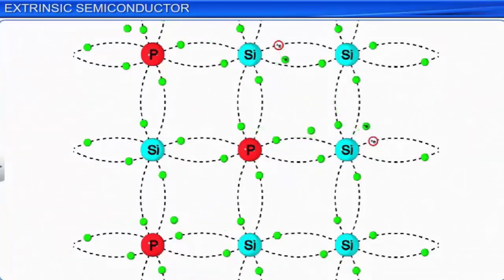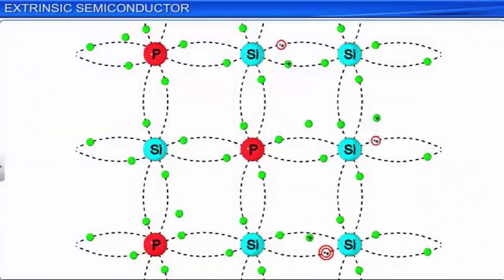Hence, in a semiconductor doped with pentavalent dopants, the total number of conduction electrons, Ne, is due to the free electrons contributed by the donor atoms, which are pentavalent dopants, and those generated intrinsically. But the total number of holes, Nh, is only due to the holes from the intrinsic source. Due to the increase in the number of free electrons, the rate of recombination of holes increases. This gives rise to a reduction in the number of holes effectively as compared to the number of free electrons available for conduction.